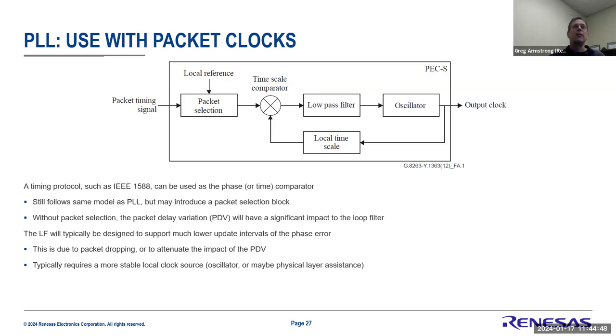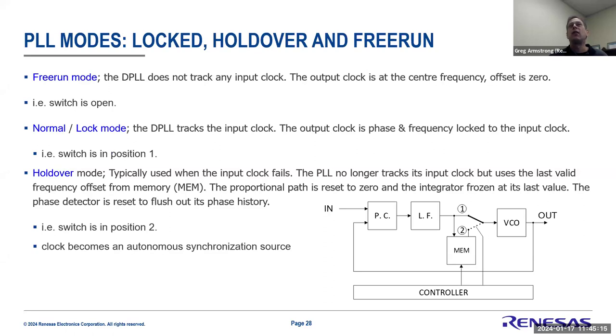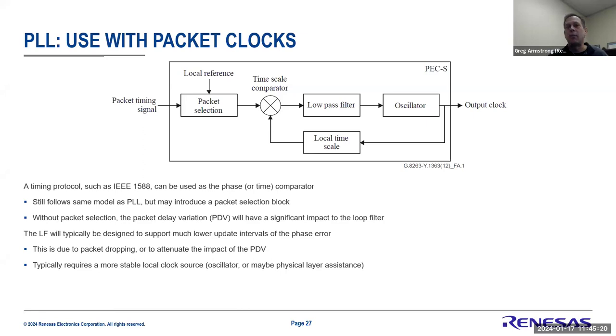But as you can appreciate, what's taken away when you go from a physical layer clock to a packet layer clock is that the packet layer clock uses a measurement mechanism like PTP to measure the offset between the grandmaster and the local clock. Well, that offset is like a phase detector offset that would come from a phase detector of a physical clock detection. So you could just feed that into a simple loop and still get all the same characteristics of the low pass filter.